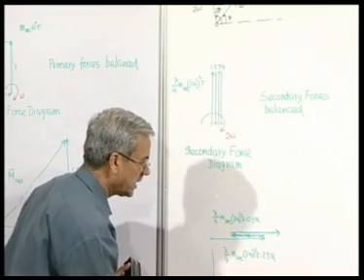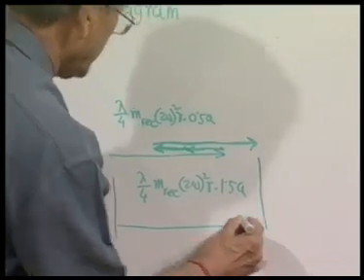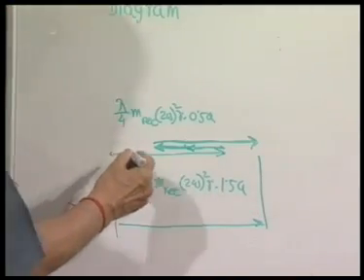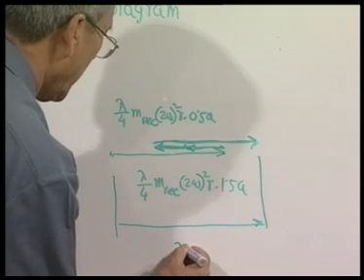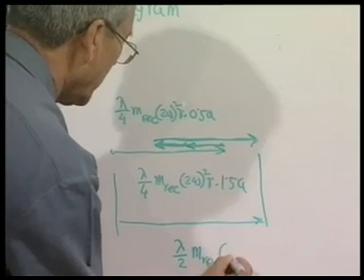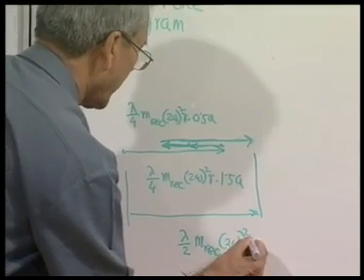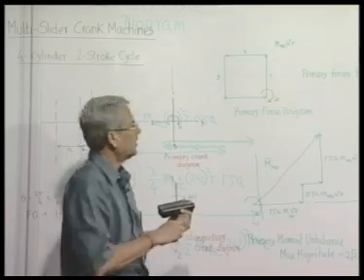So, this is the resultant magnitude of the leftover. How much is that? This plus obviously this will be 0.5. So, therefore, it will be lambda by 2 m reciprocating 2 omega square r a, and the whole thing is rotating as before.